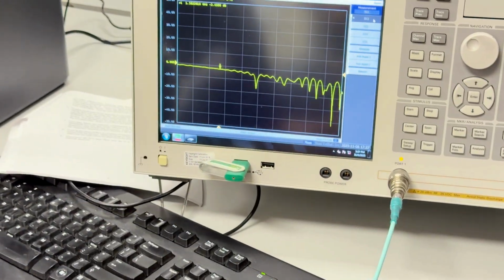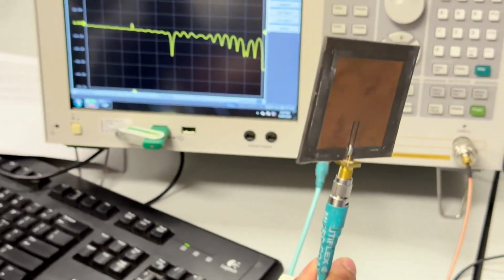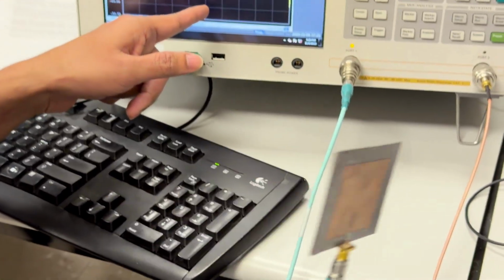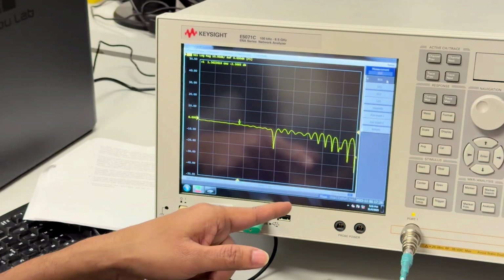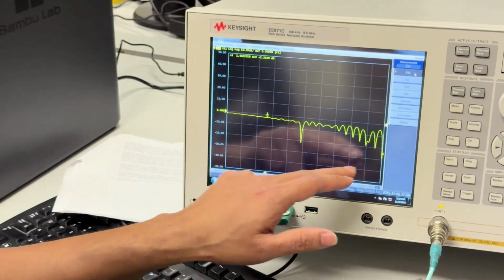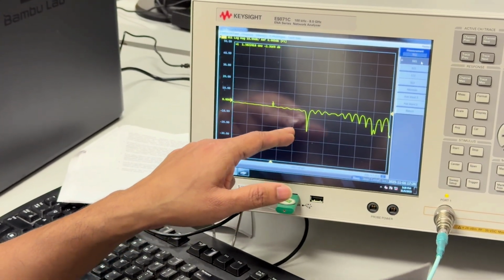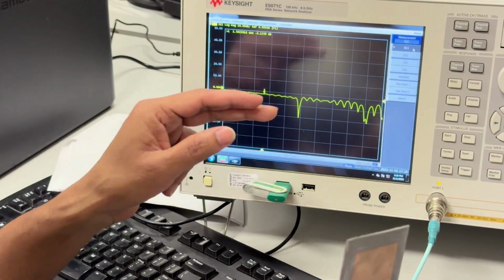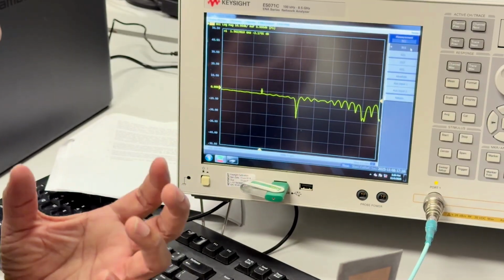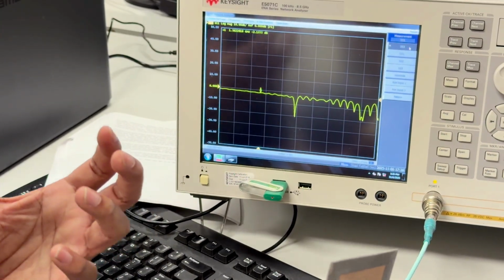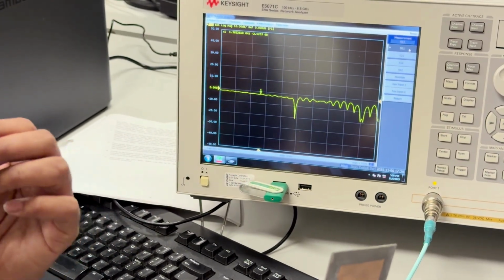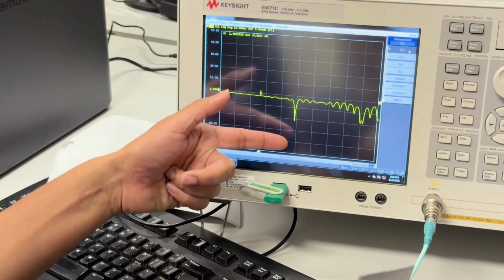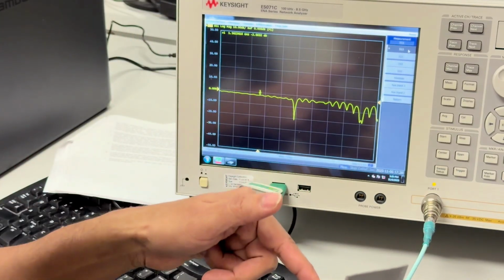And from here, as you can see, if you just change this, and if you look at the plot here, you see this is changing. But these are the notches here, the frequency notches. Remember, this is always S11. For example, if you design an antenna to be operated at 2.4 gigahertz, that means you don't want any reflection at 2.4 gigahertz. That means you want the least possible amplitude at that particular frequency.